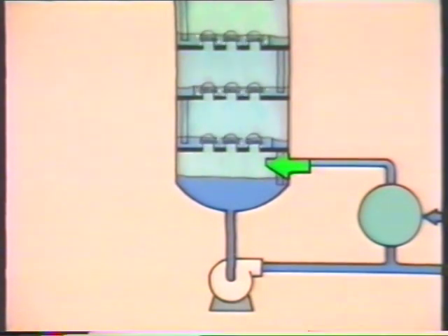These hot vapors cause any lighter part of the liquid at the bottom to vaporize and move up the tower. The reboiler is also sometimes used to provide the major portion of the heat necessary to make the distillation process work. The heat supplied by preheating the mixture is usually not enough to make the process work. The reboiler provides enough heat to cause the lighter product to vaporize in the tower. Towers that use reboilers are sometimes referred to as reboiler towers.